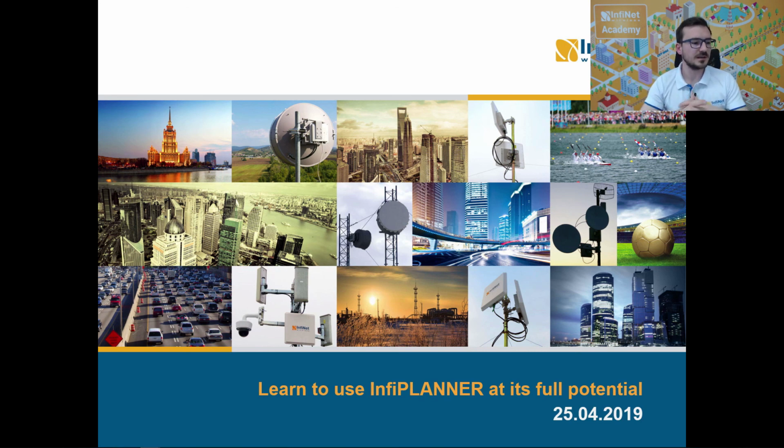Next question, is there a way to import data from Google Maps into InfiPLANNER? So the best way to import sites is with the CSV file that I showed you during the webinar. And if you have a KMZ file from Google Earth, for example, I think you can find ways, if you search on the internet, of converting KMZ to CSV quite easily. So if you are able to convert it to CSV, then you will be able to import your data into InfiPLANNER.